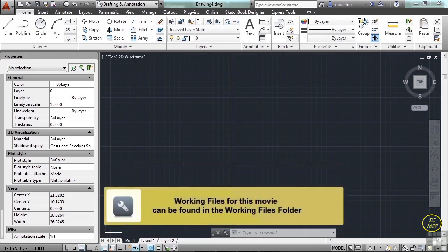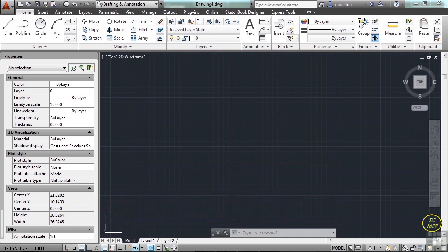Blocks are great tools that enable us to recreate similar line work rapidly. They can also contain metadata in what is called attributed blocks. A block attribute is a label or tag that essentially attaches data to your line work. Some examples of this data could be a part number, price for that part, specific comments, names, cost, manufacturer, anything